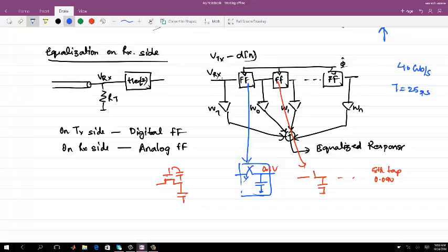You can go to the best of the technology and then say in 25 picosecond my switch should sample the exact voltage, which means 25 picosecond should be more than 3 time constants of this RC without any problem. So those things will then become difficult. It's not impossible, but then it may have another added ISI. You may try to cancel that ISI in some other manner. But if you are working at a lower frequency, 1 or 2 tap cancellation might be possible with this.